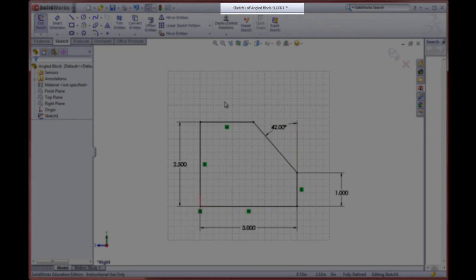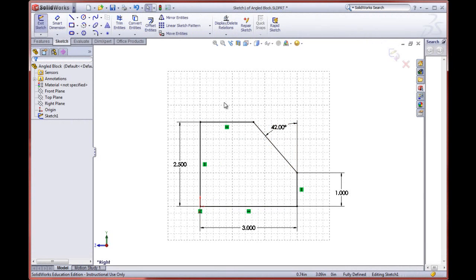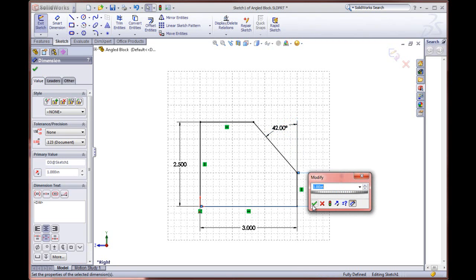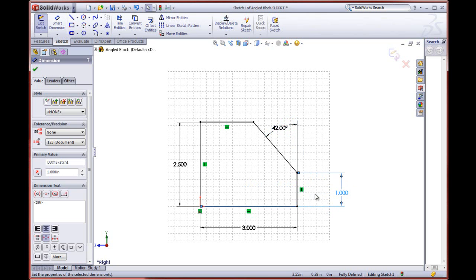A lot of people, by mistake, when they first start this, actually create a brand new sketch. Even though it's on the same plane, you can't really access the geometry to change it. So you have to be in the exact sketch, which happens to be Sketch1. So we're in Sketch1. You can make any changes you want. You can come in here and modify it. You can change the dimension. These dimensions are correct, so I'm not going to, but you could.